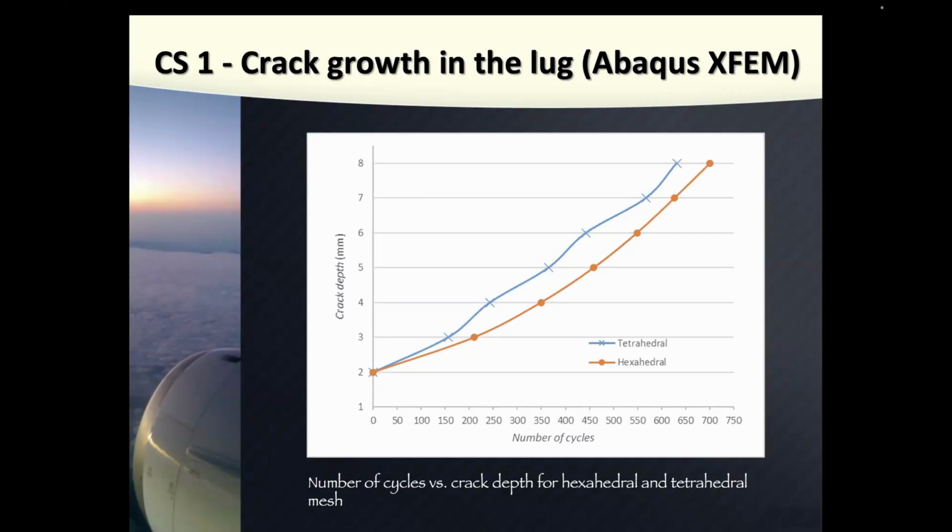We saw that in the previous simulations, but why I'm showing you this slide: be aware that mesh influences results, not only the number of nodes, but the type of the element. And we can see that the number of cycles here is very low, which is expected. Why? Because this element should be a fail-safe element. It's not allowed for any crack to appear on this element, because it's under very high stress. So it must be made of very strong steel, but the steel is very expensive.